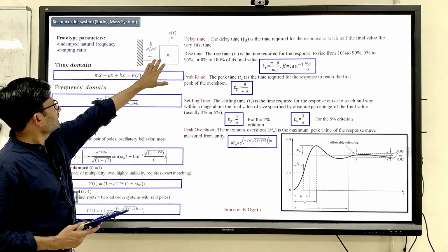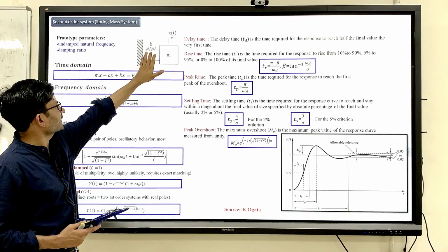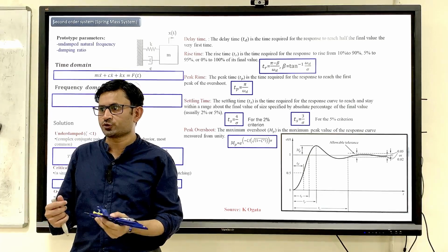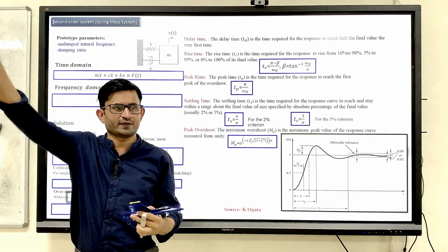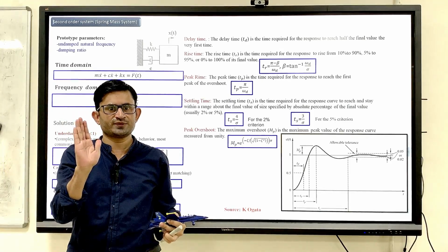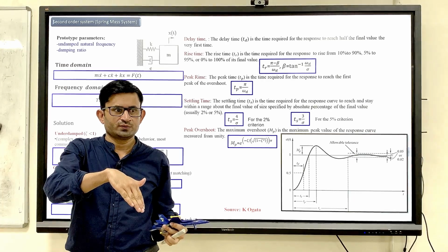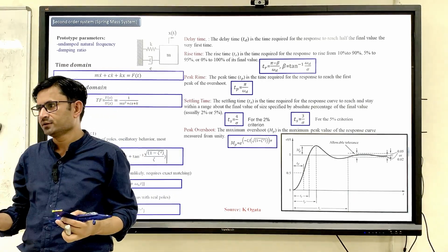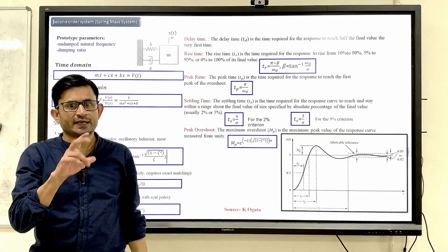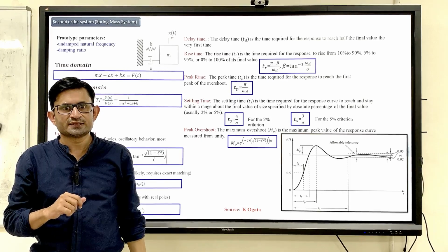So this is a spring mass system where K is the stiffness. K will tell you the restoring characteristics like Cm alpha, right? Try to pitch down. If you try to increase the pitch up, it will try to pitch down. Inherent tendency, right? So restoring force will be provided by K. And what is C? C is the damping.